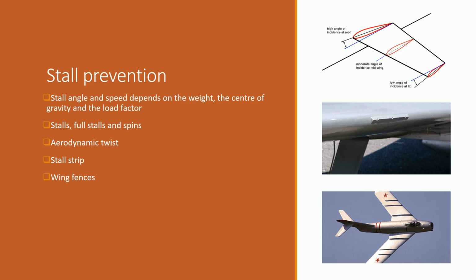At the wingtip, if the fences weren't installed, the flow can almost all be spanwise. So the flow will be travelling from the root to the tip, instead of normally from the leading edge to the trailing edge. The flow of air over a swept wing usually causes a pitch down moment. This is due to the centre of gravity acting in front of the centre of lift on most swept wing aircraft. However, if the wingtip stalls, then the opposite is true. The aircraft tends to pitch up, causing a more severe stall, which is why wing fences are necessary to prevent stall.